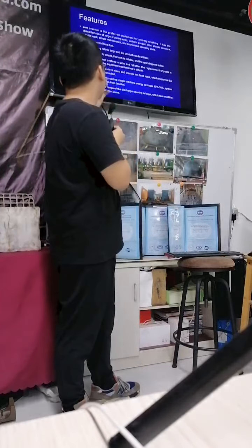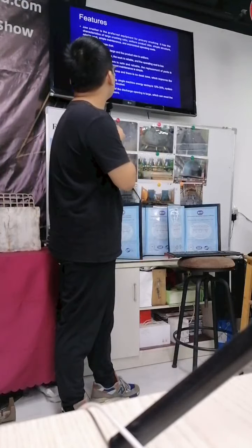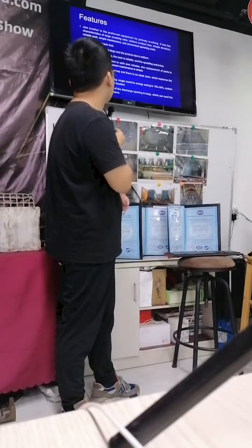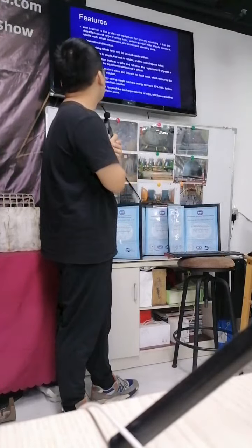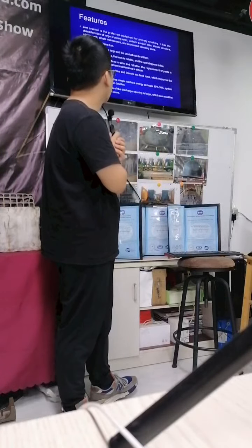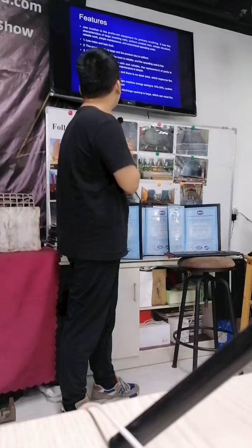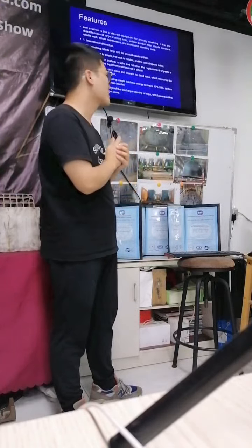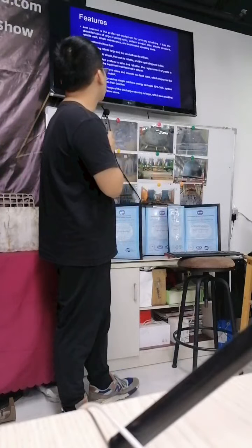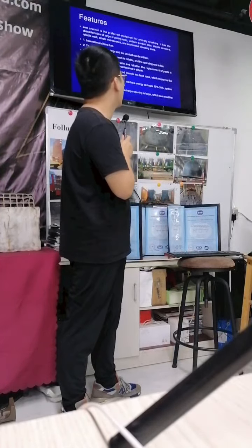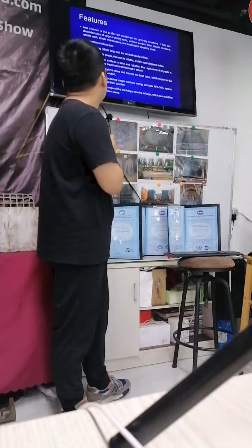And it has about 7 advantages. The first advantage is it has low noise and less dust. And the second advantage is the crushing ratio is large and the product size is uniform. And the third advantage is the structure is simple, the work is reliable and the operating cost is low.